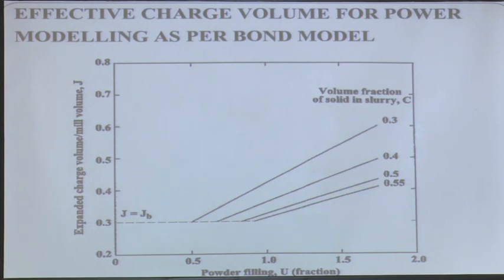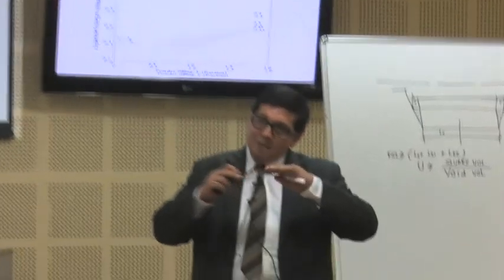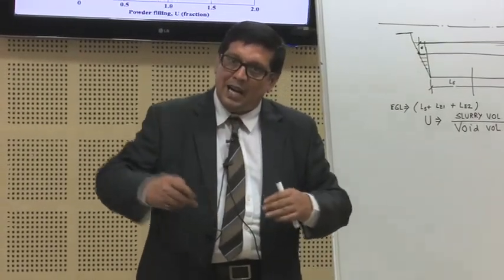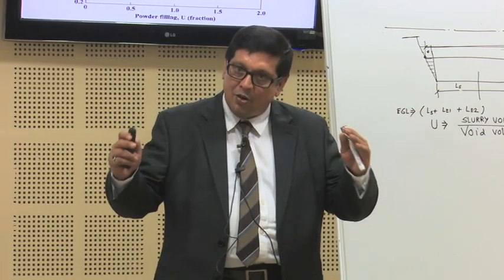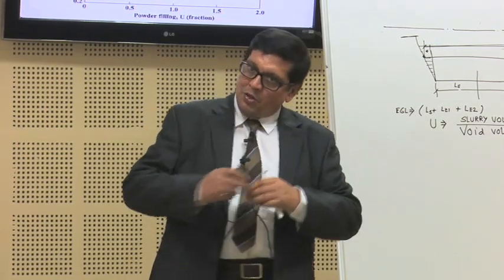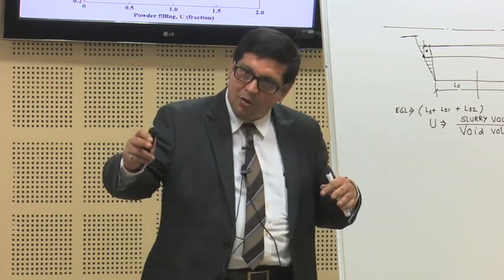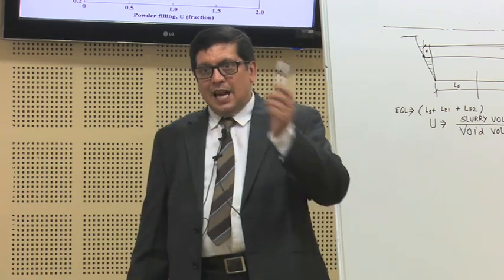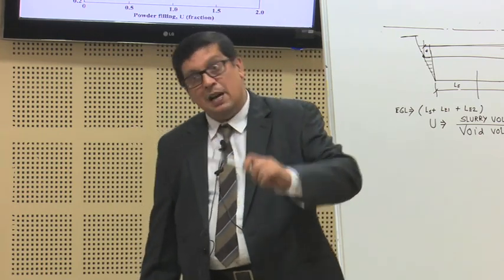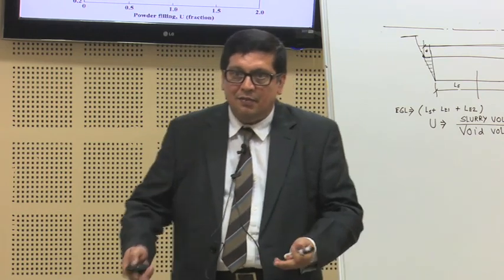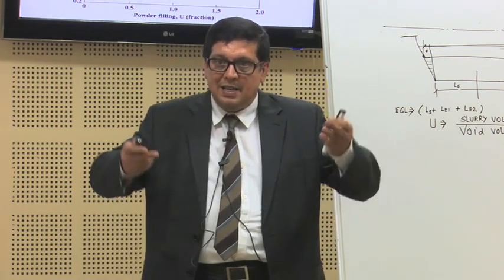I said, two things are different. What is the difference? One is only the ball charge volume. Now, if I consider all the interstices in the ball are filled with slurry, then the same volume of charge will hold or will make higher weight, because with 40% porosity there has to be some value of the weight. When porosity is nil, the weight will be more. Now, if you consider that more weight and divide that by the actual bulk density, then you will find the fill percentage has gone up, as if the charge has expanded.